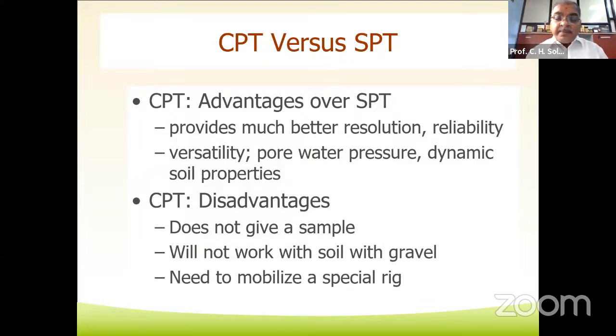Whereas the disadvantages of the CPT test are mentioned here: it does not give a sample, will not work with soil containing gravel, and needs a special rig to be mobilized. Special equipment is required in the performance of the static cone penetration test.